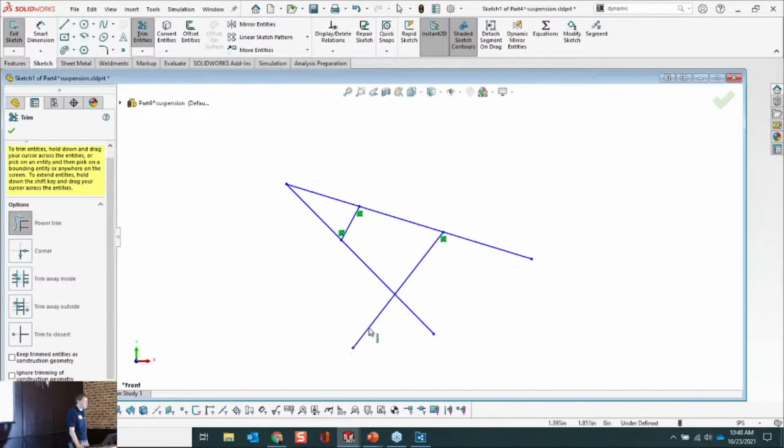And it's pretty nice. So you just hold down left click and you slam through the line and it'll get rid of it. But it's the only trim command that'll let you undo without having to undo and get out of the trim command. And you're in the trim command the entire time. So that means you could go forward and backwards as long as that mouse button is held down. And it's simple. It's just subtle. It's very subtle. Now, once you lift off the mouse button, there's no reverse. You're there. You can't do it. Just like if I start again and try again, that other red dot from when I was over here, it's not there. So I do use power trim pretty much exclusively.